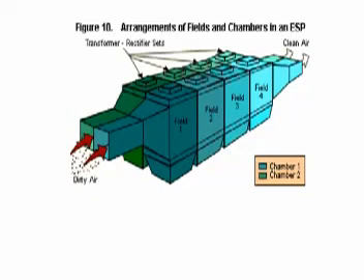Because the gas quantity may be very large, you don't want one large unit; rather you divide it. The idea of dividing into a parallel process will always give higher efficiency. If something goes wrong in one stream, and things can go wrong, you continue to operate the other.